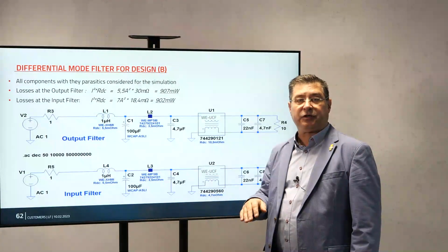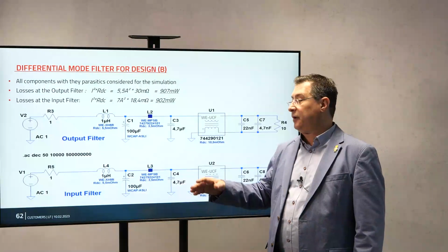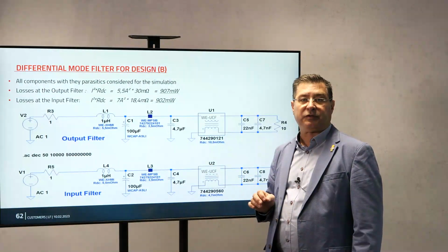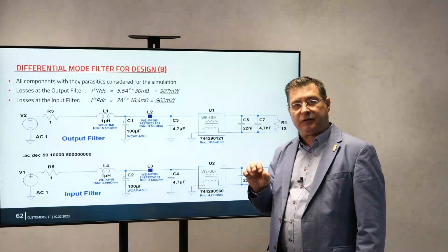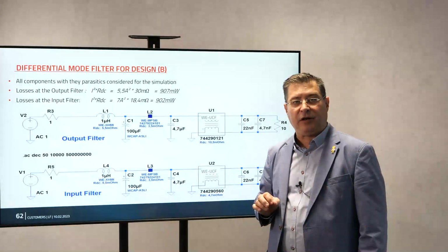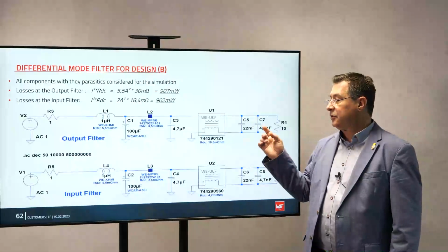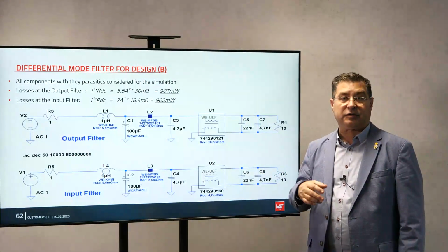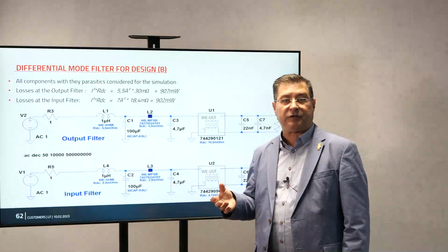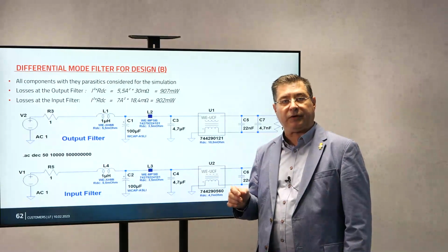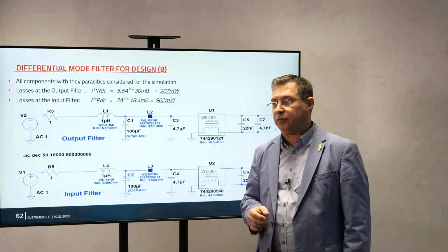So your efficiency, even if you have a perpetuum mobile, because of the filter, will be only 98%. So if you are scratching for this 95% efficiency, you have to consider also the resistance of the filter, because sometimes you could destroy the efficiency only because you chose the wrong component to save a few cents.